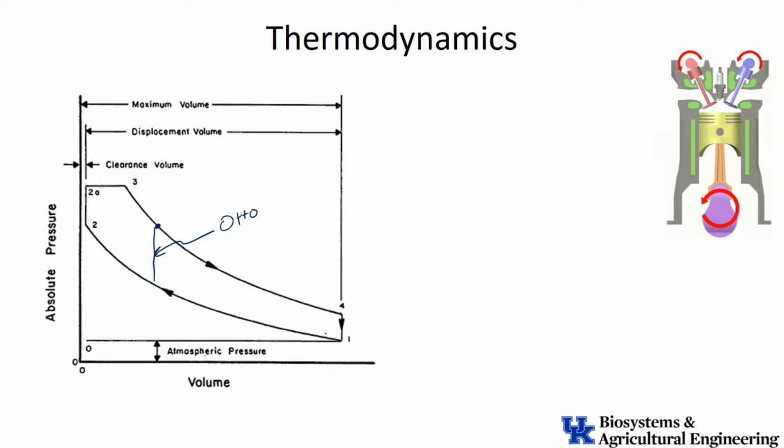And so his thought was, hey, if we can put some fuel in a cylinder and we start down here at bottom dead center, we're going to compress that cylinder. We'll compress the air-fuel mixture to some point. And again, this is the spark ignition engine, so we can't compress it too much or that fuel is going to auto-ignite like we talked about before. At this point, we reach our maximum compression right here. We're going to ignite the fuel. The pressure jumps way up in that piston, and now we're going to drive the piston back down.